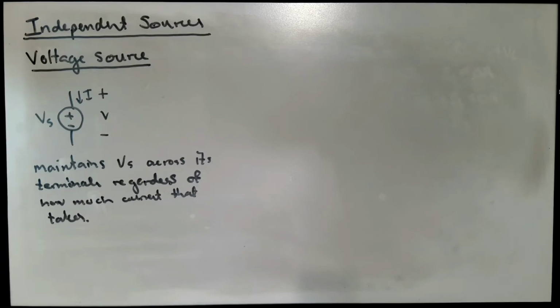And you can imagine that a stack of, let's say, two 1.5 volt batteries makes 3. So 8 1.5 volt batteries stuck in series with each other would add up by KVL to 12 volts. And you could imagine that that stack of, let's say, AA batteries won't be able to put out as much current as a 12 volt car battery would. And so a 12 volt car battery might be a better 12 volt voltage source, or a better approximation to a 12 volt ideal voltage source over a wider range of currents than our poor AA batteries would.